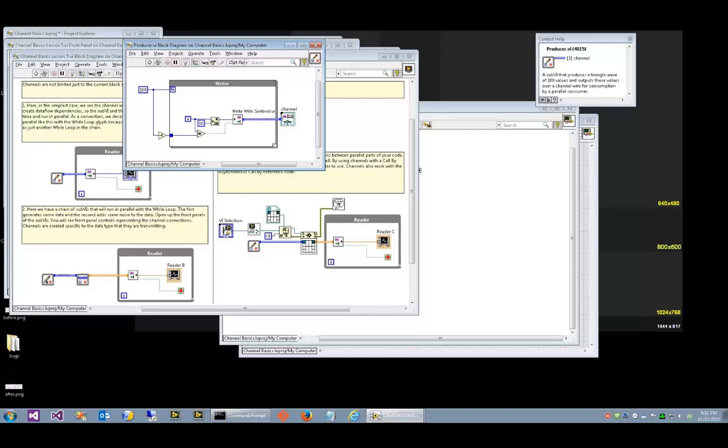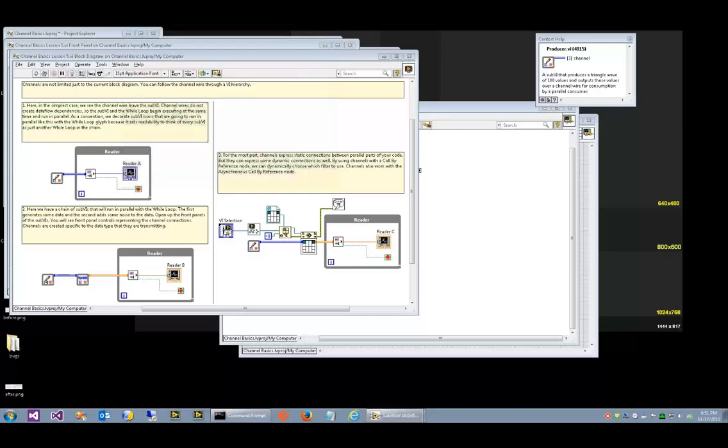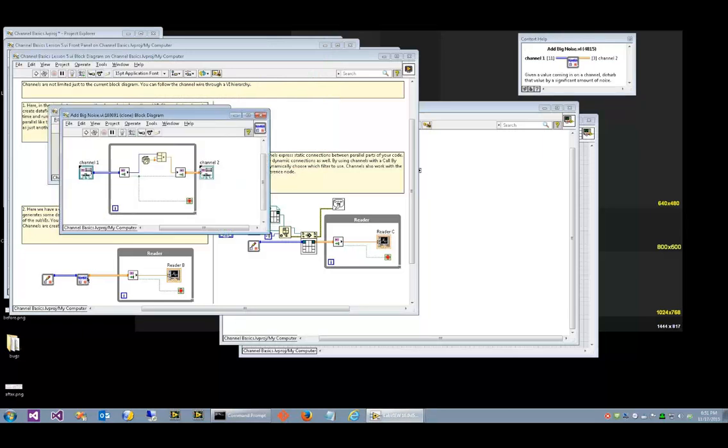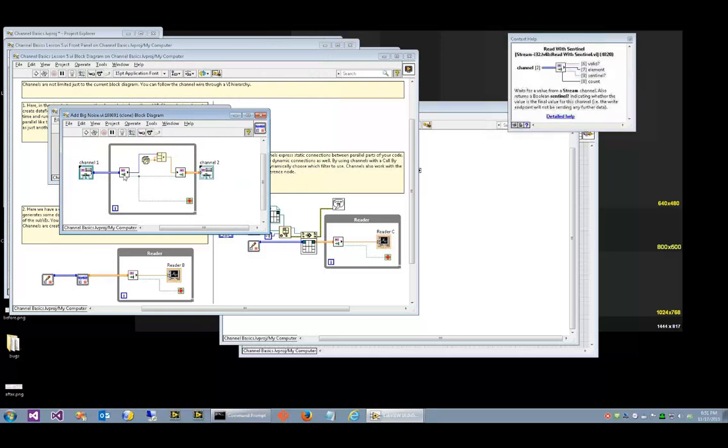And you can then follow that wire up into its caller, follow it across, back down into the sub-VI, and find the matching read node. That's the biggest thing to get around. Exiting the connector for that VI. Yes, it is not a synchronous wire. It is simply a connection that indicates there is communication between these two parallel VIs. Yes, that is exactly the raise-your-eyebrows, am-I-comfortable-with-this moment.